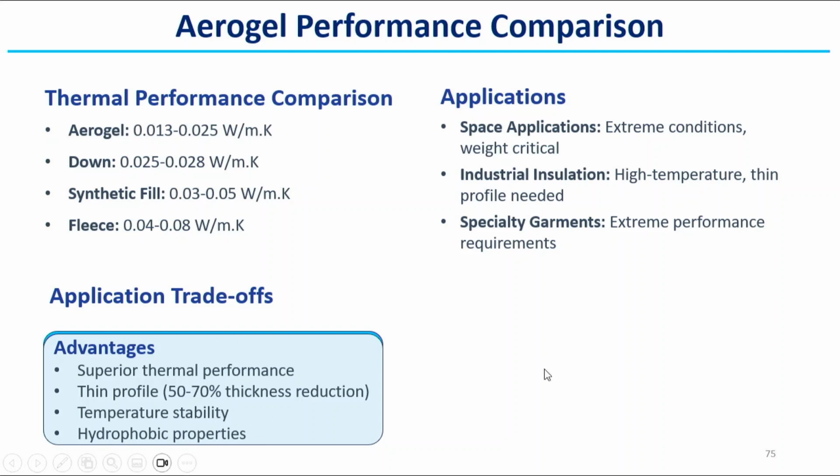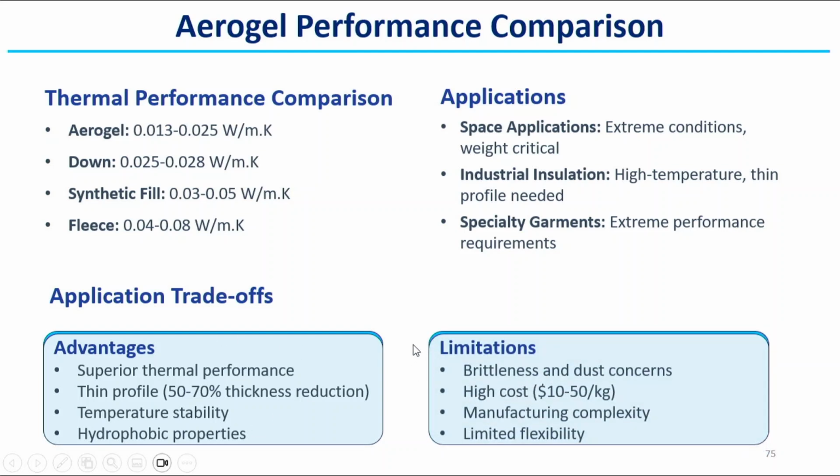These are the advantages, but if you see the limitations, most aerogels are brittle and dust formation takes place, that is a concern. The aerogel is very expensive as compared to other materials, it is very difficult to manufacture, and it is not flexible. So, due to all these limitations we have to consider the particular applications.